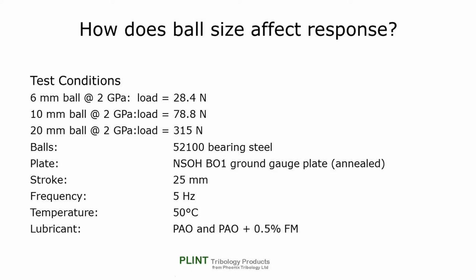The balls were 52100 bearing steel, and the plates were ground gauge plate, annealed. The stroke was 25mm, frequency 5 Hz, temperature 50 C, and once again we used PAO and PAO plus 0.5% OFM.